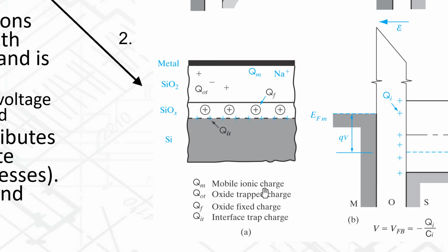We don't have time to go into all the details of that, but the key point that I want you to know is that these were all liquid processes, and if the water in those processes was not clean, let's say you use city tap water instead of deionized water. City tap water, if you measure it, you'll know that it has a lot of different ions in there. It has calcium ions, it has magnesium ions, and so forth. And those ions can actually bury themselves into the semiconductor and get stuck there. And what happens is that they actually get stuck inside the gate oxide.